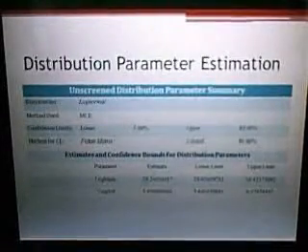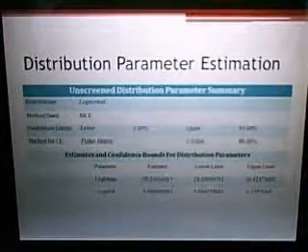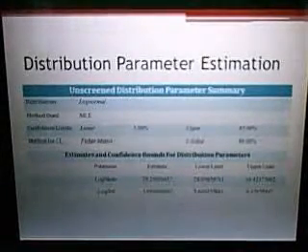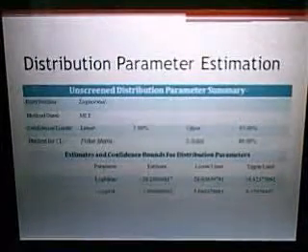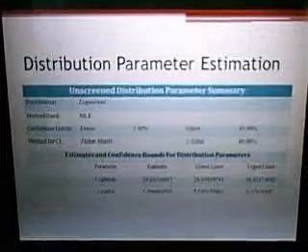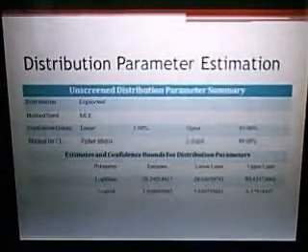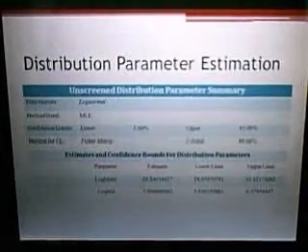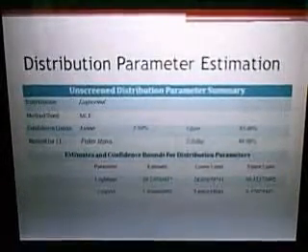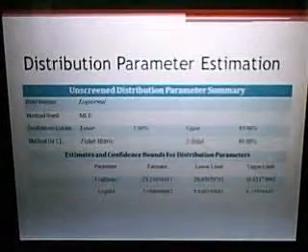Once we have determined the distribution that we're going to follow, we use Weibull++ to determine the parameter estimations. In this case, for the unscreened distribution parameters, we can see that we used the MLE methodology. We had confidence limits of lower 5%, upper 95%, and we also have a two-sided Fisher matrix confidence level of 90%.